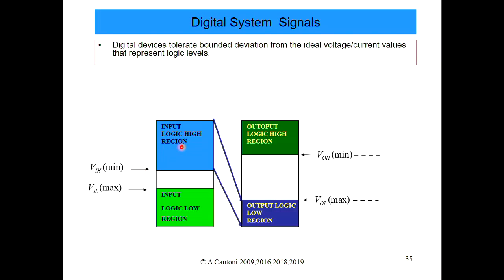And the important thing is that, for instance, say this was an inverter, the actual output of the circuit, digital gate or integrated circuit, will map that particular voltage range into a more restricted voltage range. So in this case it's an inverter, we map a 1 to a 0. But we can see that the output voltage range is a smaller range than the input voltage range. And similarly for the high output, the output 1 is in a smaller voltage range than the input voltage range, which is recognised as a 1. So that gives us a noise margin.